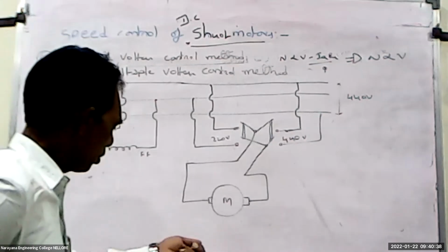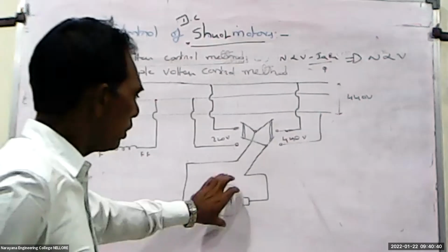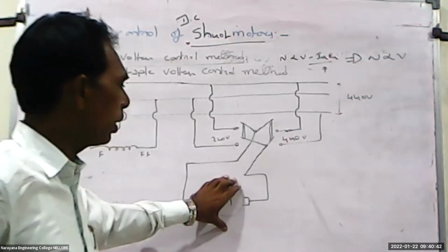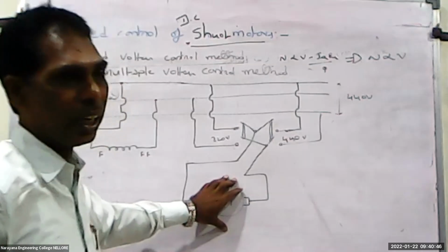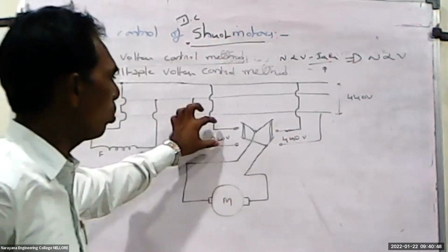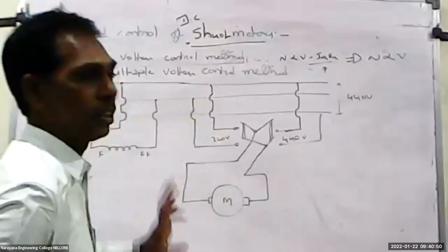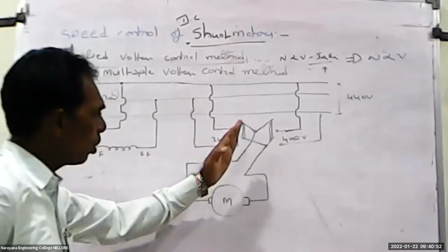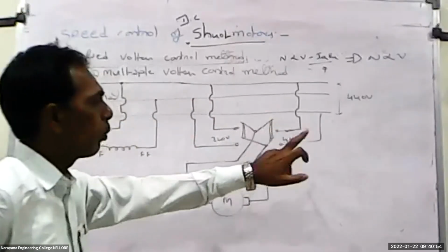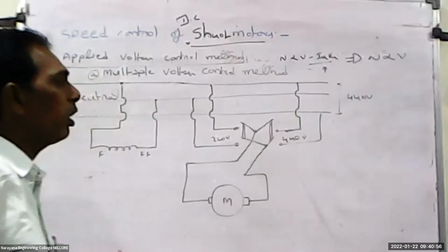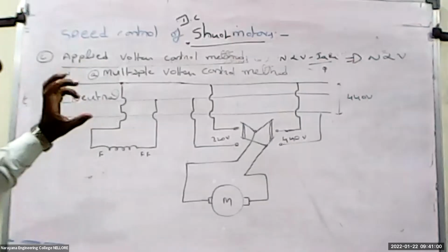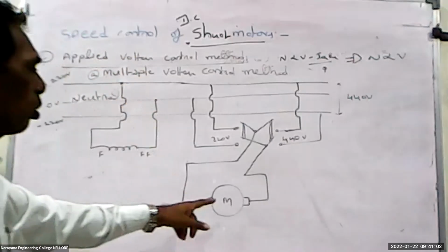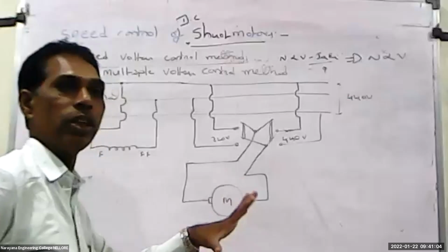Suppose you observe here, if you connect this motor, the previous case is approximately 220 volts or 230 volts. So the motor is designed to be suitable for single phase. If your motor is connected to this side, the voltage is 440 volts. 440 volts means it is suitable for a 3-phase supply. That means the rating should be a high value, so automatically the design should change.